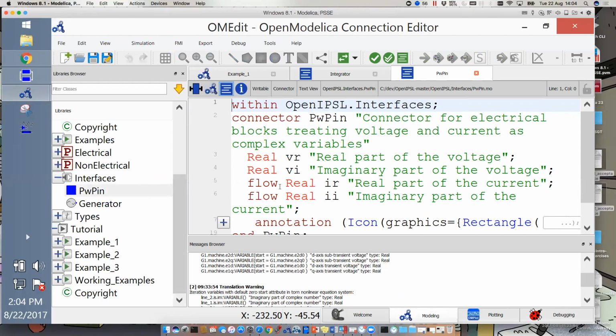This is the only thing that is relevant for us, but people working with thermodynamics have a lot of flow equations. So for them, the flow is a very useful construct to use. We only use it for the current, really. Because in other parts of our system, we have a control system that has an already defined direction. But with the flow, as I was explaining this morning, you don't define the current flow in the model until you're simulating it. So it has to be able to decide how it goes. Okay, so that's the most important interface.